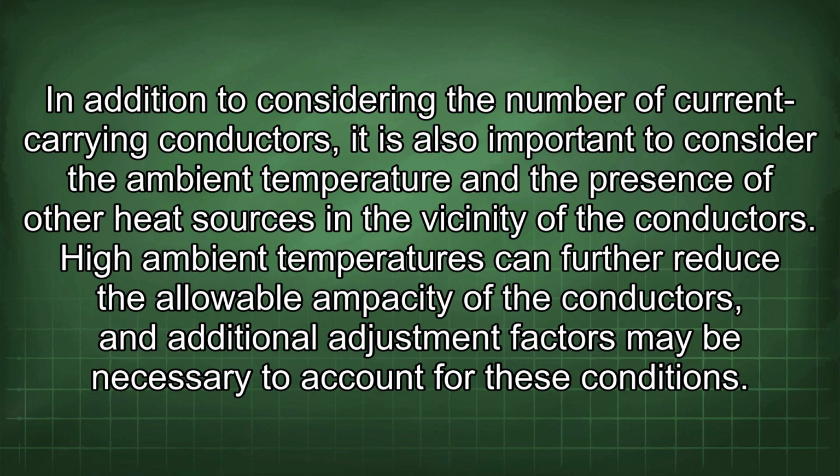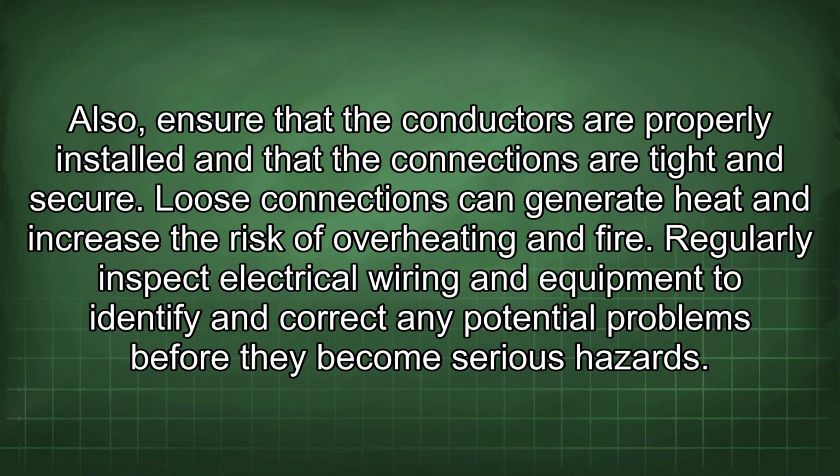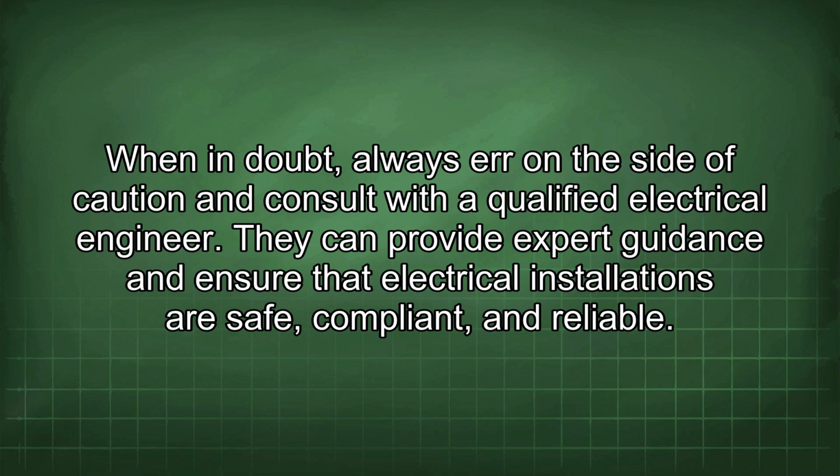High ambient temperatures can further reduce the allowable ampacity of the conductors, and additional adjustment factors may be necessary to account for these conditions. Also, ensure that the conductors are properly installed and that the connections are tight and secure. These connections can generate heat and increase the risk of overheating and fire. Regularly inspect electrical wiring and equipment to identify and correct any potential problems before they become serious hazards. When in doubt, always err on the side of caution and consult with a qualified electrical engineer. They can provide expert guidance and ensure that electrical installations are safe, compliant, and reliable.